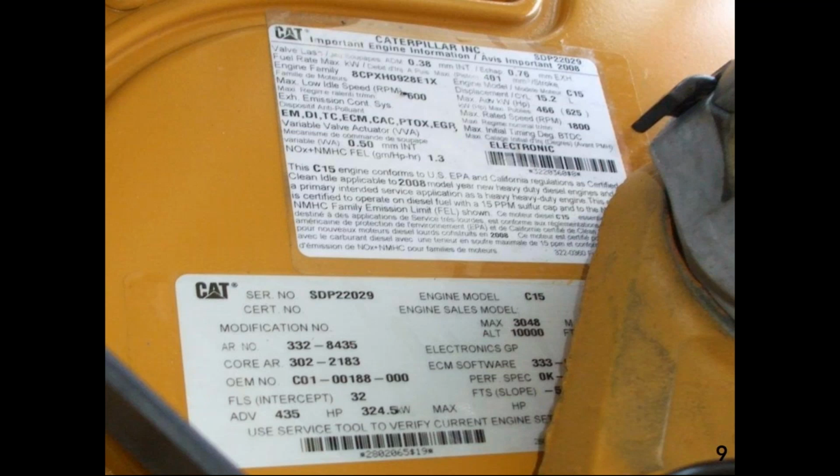CPX is the 3-letter designation for Caterpillar. H is the 5th character, and the last one was an L. L is generally off-highway, off-road. H happens to be on-highway, so this is an on-highway truck. Now, Caterpillar decided not to use liters. They decided to go with cubic centimeters. So 0928, 928 cubic centimeters.